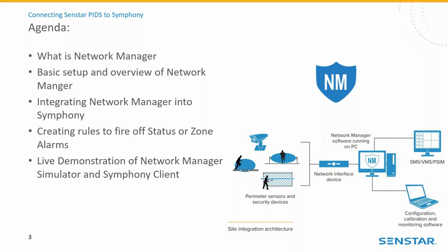Network Manager can reside on the same PC as the management software. So today I'm running in my environment both Network Manager and Senstar Symphony on the same server. Or you can install Network Manager, if you have a lot of Network Manager instances, let's say you're using the full 10, on a dedicated PC as well. And so Network Manager connects to the network sensors via a gateway hardware, and that connection or media type is either 422, fiber, or Ethernet. And just lastly on this point here, Network Manager is not only a point of integration just for Senstar Symphony.